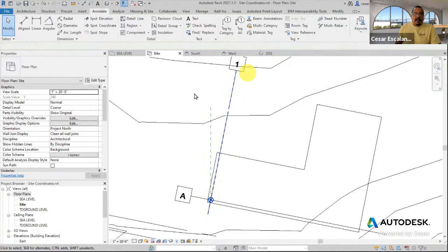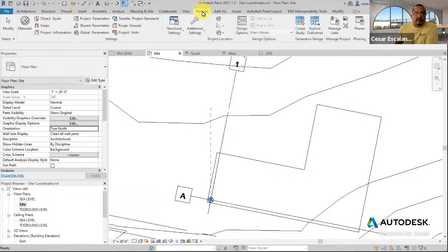So in the project, I'm in the side view. The side view, make sure you establish this to be the true north, because this is what the true north needs to look like. And this is important, make sure the true north is aligned with the view first, and then execute the command. And then go to the Manage tab, site location, and then